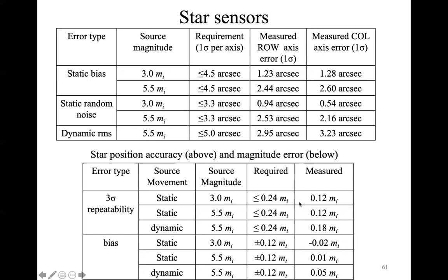What does it mean? That if you have stars with magnitudes that differ by 0.1 apparent magnitude, those two stars can indeed provide ambiguity. That's the reason why, when you want to identify and acquire stars, you need to use multiple stars, because even if one star can be confused with another one, if you have a configuration of multiple stars, this error can be definitely lower.